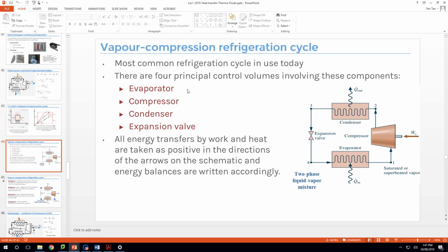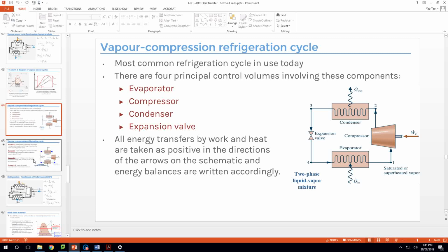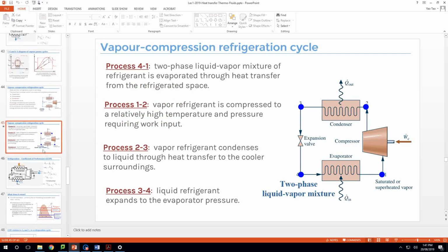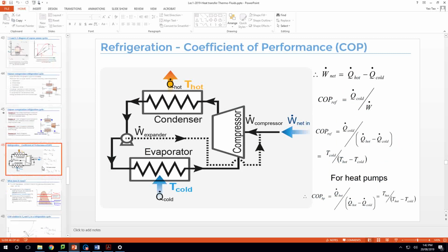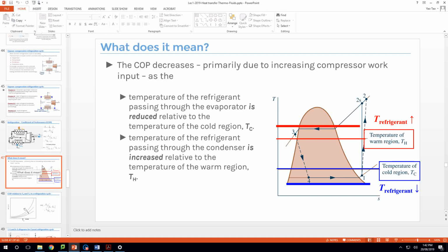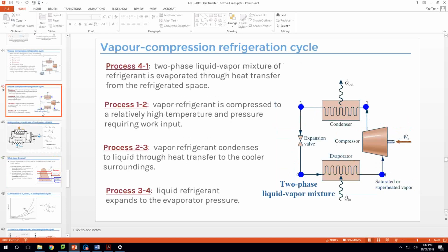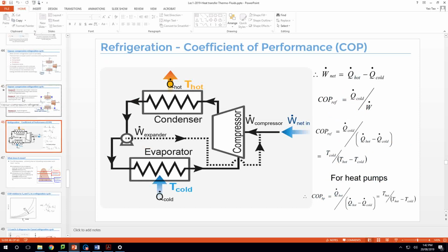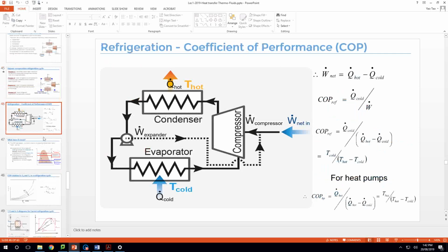For example, the evaporating section, that's cooling capacity, the compressor, that's work input, and what's part of condensation. We have done the practice, and you could remember that the heat transfer rate would be m dot times delta H. So which delta H you are looking for would be each part of the heat transfer rates.